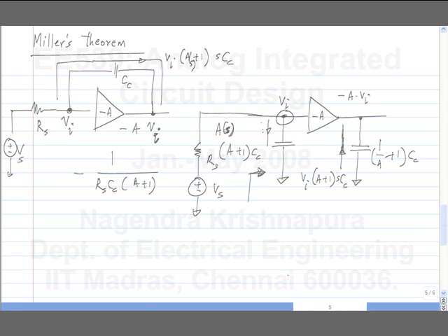The fact that it's in the right half plane is significant when you want to use it in feedback systems. And the poles can be split by increasing the value of CGD. So that's a method for compensation that we'll use afterwards.